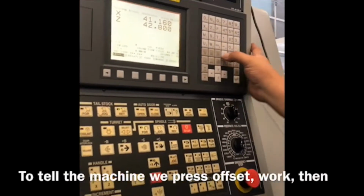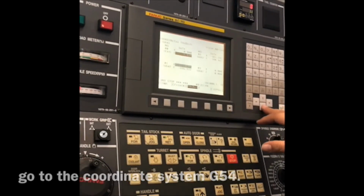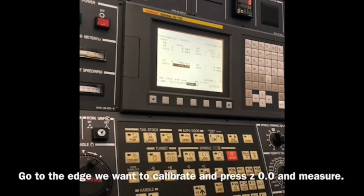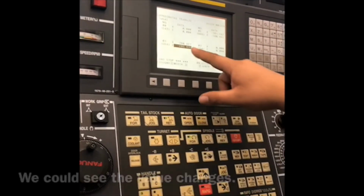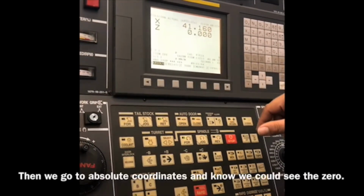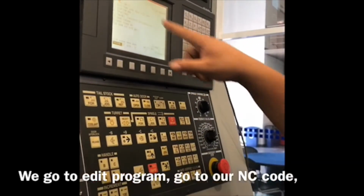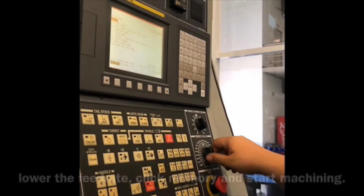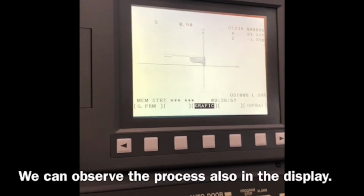To set the offset, we press offset word, then go to the coordinate system G54. Go to the edge we want to calibrate and press set 0.0 and measure. We could see the value changes. Then we go to absolute coordinates and now we could see the zero. Once we define our zero, we can start. We go to Edit Program, then go to our NC code, lower the feed rate, click Memory, and start machining. We can also see the process in the display.